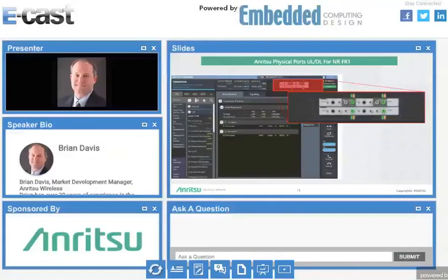So that's for millimeter wave, and then there's a shot there showing you the uplink and downlink for sub-6, because sub-6 comes directly out of our equipment there. So you can always separate the uplink and downlink ports as well. This is in bidirectional, so this is showing, say, a MIMO, or I'm sorry, a single antenna with 4 carrier aggregation. So you have the 4 different carriers there with different uplinks and downlinks going to the same ports.